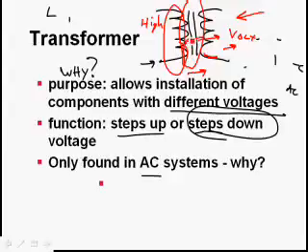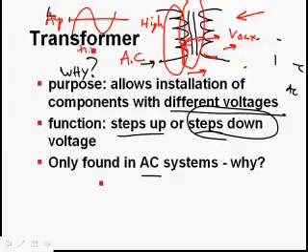Then when these lines of flux collapse, because remember this is alternating current, and so we've got a nice sine wave going on, the number of amps versus time, the amps are going up. As the amps are going up, the lines of flux are expanding. Then as the amps go down, these lines of flux will collapse. So we have movement across the wire, movement back across the wire. Then we have electrons going in the opposite direction, but they're getting more of them. Remember, this distance here is just quantity. So lines of flux cross the wire, but they're opposite polarity, so it causes current flow in the opposite direction.